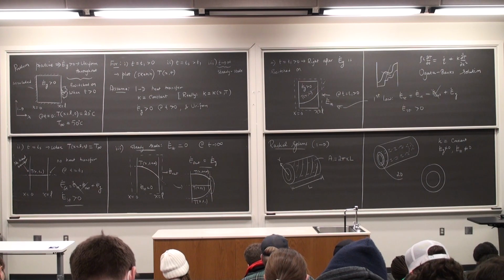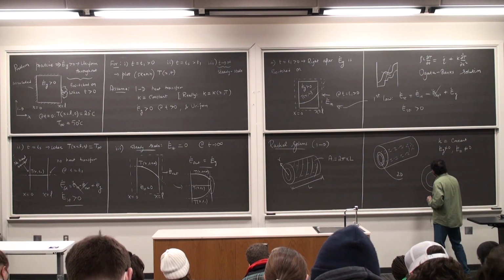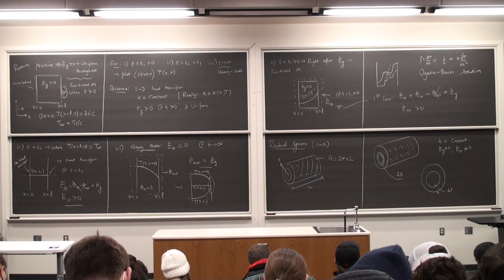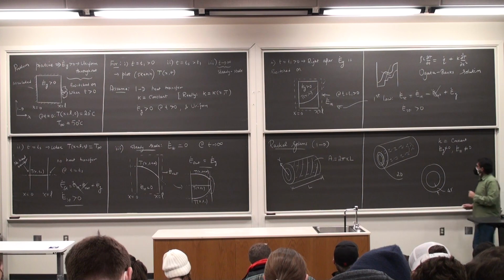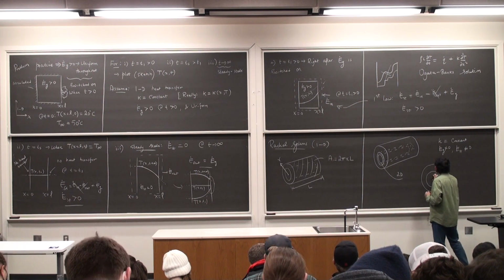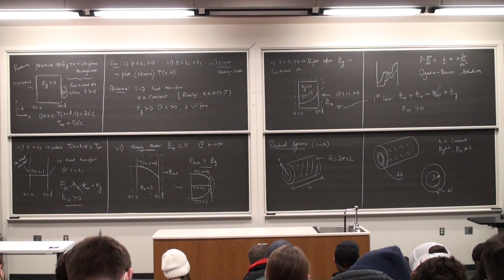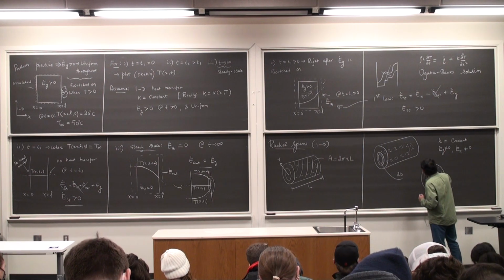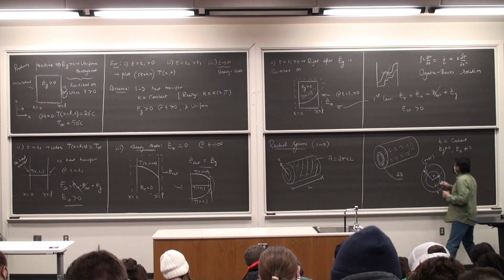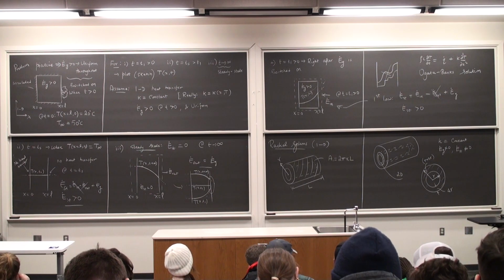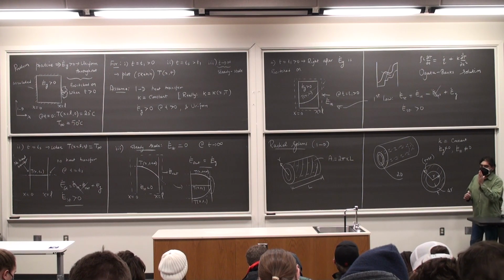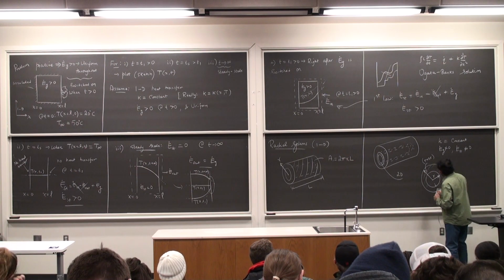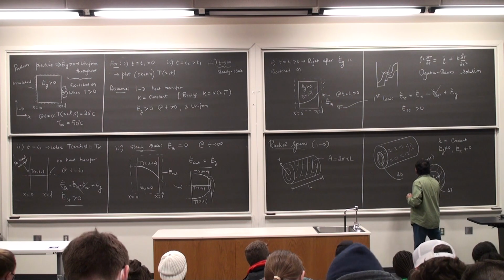I'm going to say that the thickness of this volume element is delta R. Then I'm going to say that the radius at the inner ring, this is almost like a cylindrical shell, radius at the inner ring is R, which means that the radius of the outer ring of this volume element is R plus delta R. And we are going to say that heat transfer is taking place starting from the location R is equal to R and going out at the location R plus delta R. Okay, so if I look at the direction of heat transfer, it's all radial.